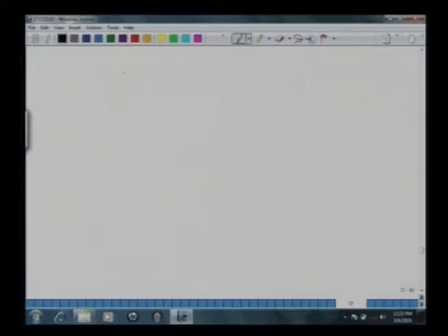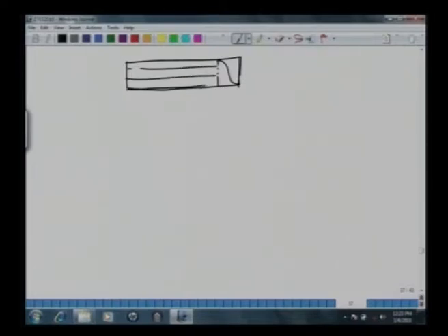Now if you plot further down, after some time you will expect that this MTZ has arrived almost at the exit. That means now the profile is like this, and this is the region which is now totally saturated. So this is a saturated zone, and this is a region where we say there is an activity, an active zone. All right. So now we have reached the region of L3, and let's say L3 prime.